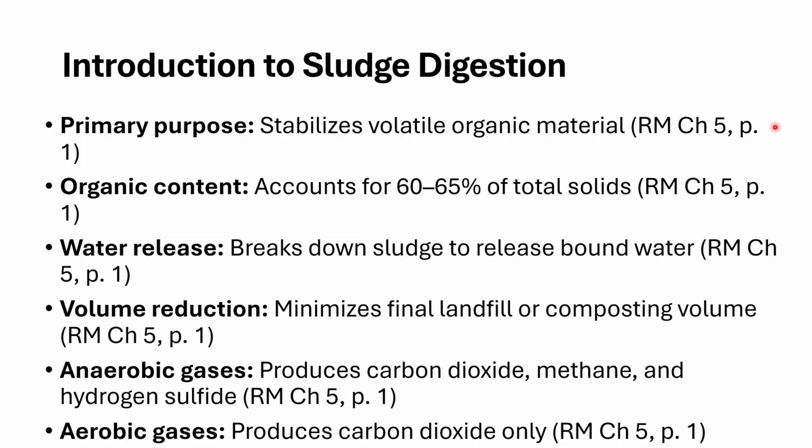In addition to that, we went through some grit chamber work where we tried to settle out sediment and sand or even coffee grounds. Using air flotation, we allowed the separation of organic suspended material to float up to the top of that influent, and the heavier inorganic sand or pebbles to settle down, where we send them to a grit washer to remove any organic material and any potential for odor-causing organic material to stay on that grit.